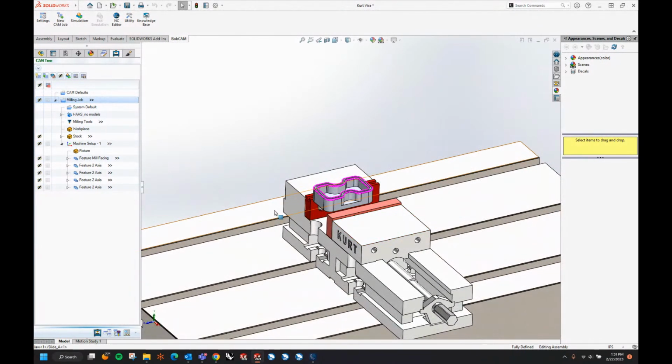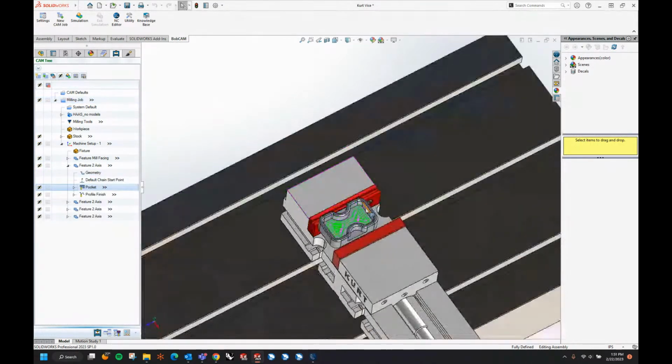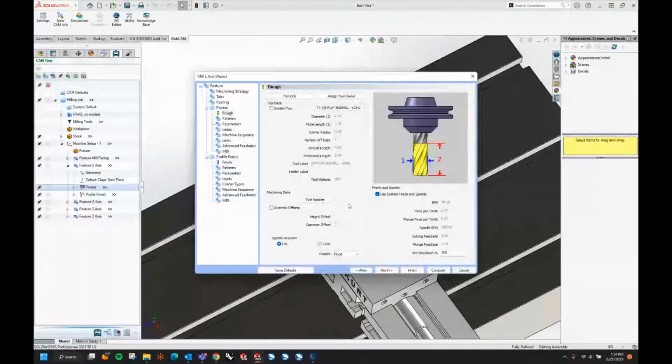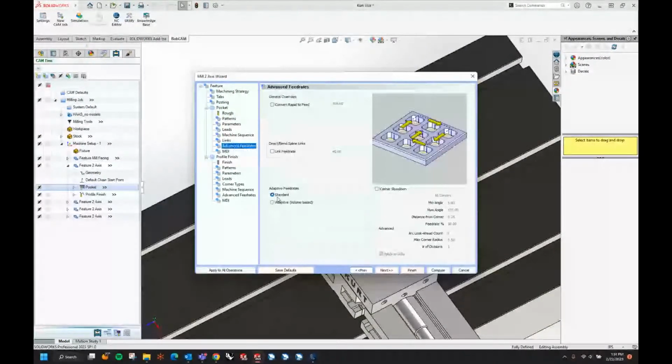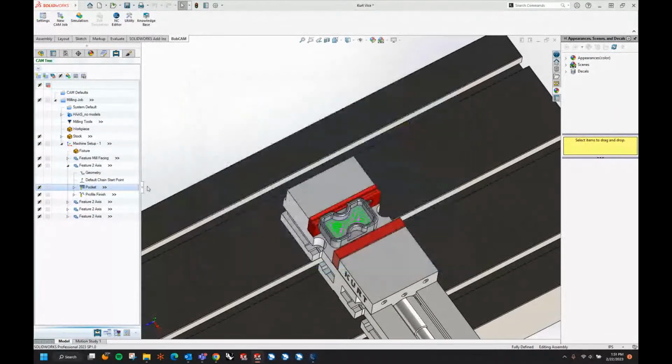All right. Now this one should be done, but I do want to go back to that last file, and I think I actually closed it. I did. So let's take this one and use some of these feed rate control options. So we've already got this pocket, which this pocket has just square corners. So let's go ahead and edit this one with the advanced feed rates. We'll do the corner slowdown. So let's say I do 50% slowdown, 16th before a wall. And I'll even do that. Yeah, we'll just do that on the pockets.